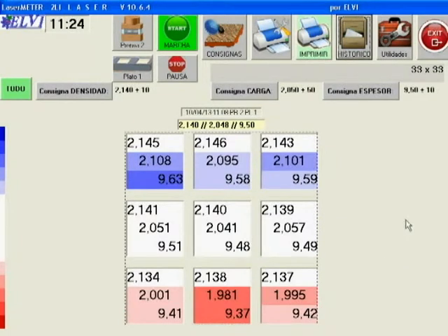The first thing that we see on having gathered the information are the setpoints of work with which the tile was pressed. We can observe the setpoint of density, with its range of work. The setpoint of load of clay, with its corresponding range. The setpoint of thicknesses, with its corresponding range.